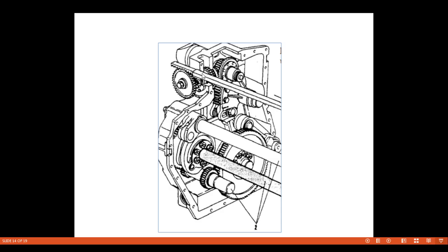So this is the rod moving inside and outside of the shed. So how is the drive? We can see here the dotted rigid rod is there and it's meshing with the pinion. This pinion is moving clockwise and anti-clockwise. When it moves clockwise, the rapier goes inside the shed, and when it moves anti-clockwise, the rapier goes outside the shed. In the telescope, here the telescope will be there like this. So here double space will be required.